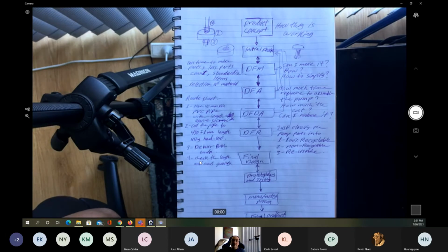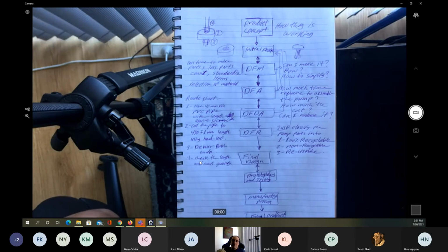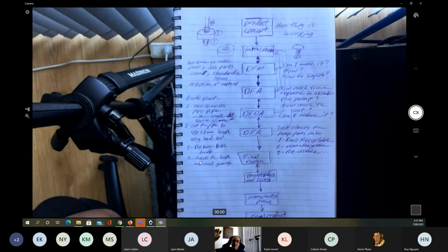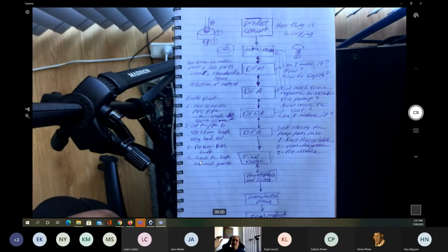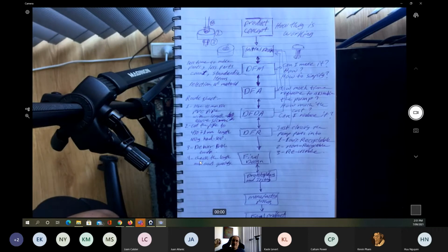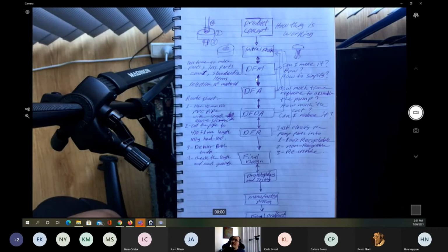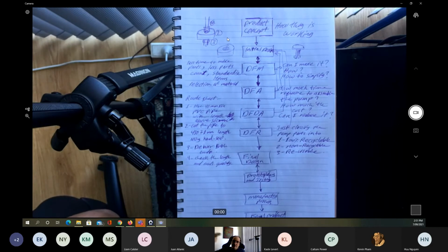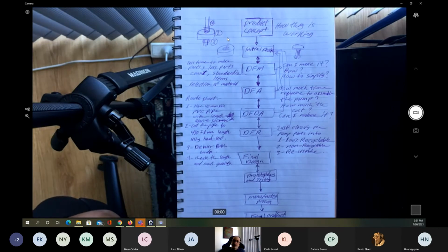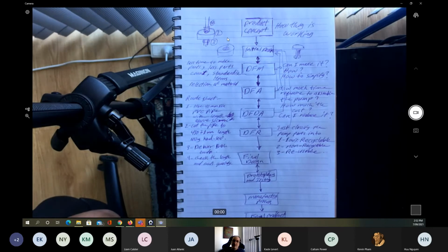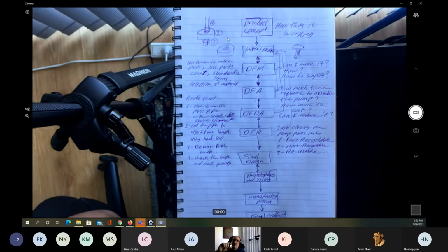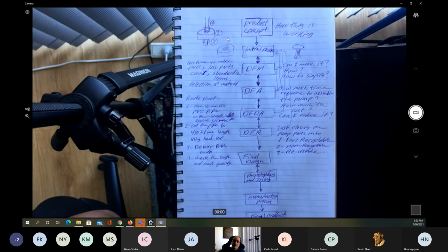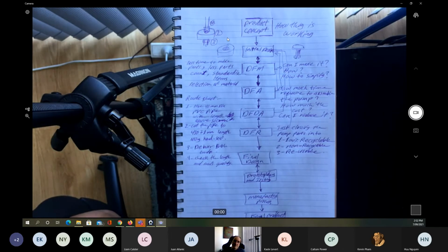So the route sheet is the sequence of the machining of the part to get the final product. We start from the raw material and put the sequence of the machining in a reasonable way. So we're not going to do, for example, the threading of a hole before making the hole itself. What's coming next should be at the end, not at the beginning. The raw material is what we start with, then the processing of the raw material into a semi-finished part, and the finalizing process.